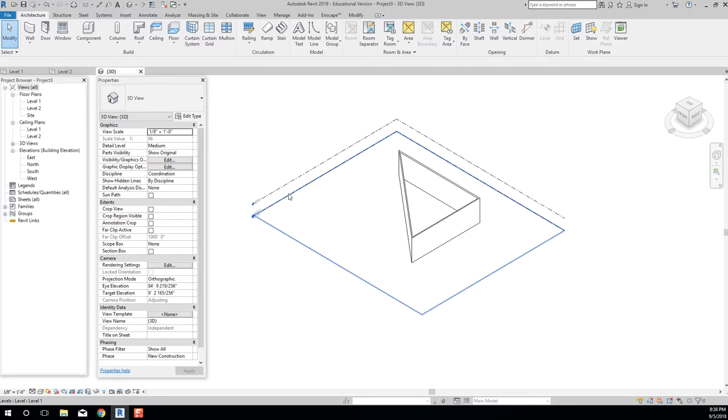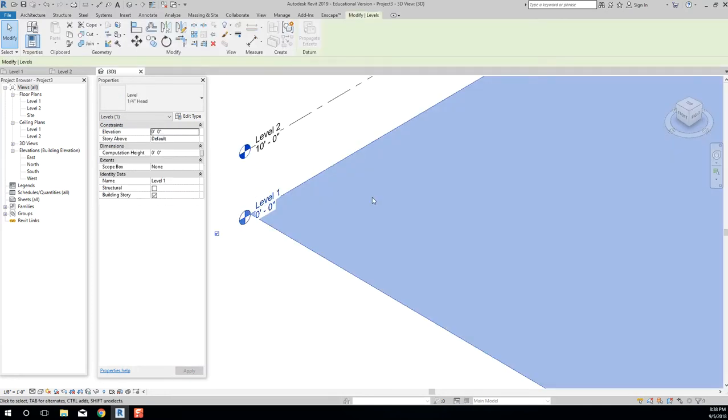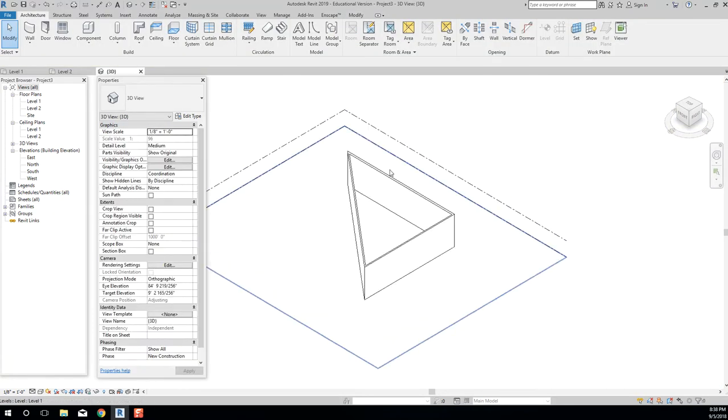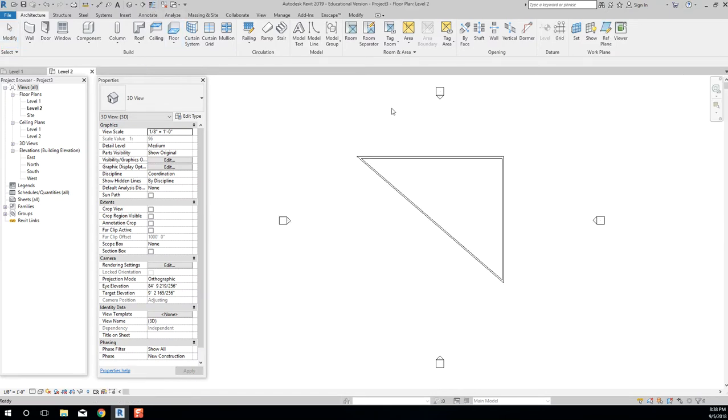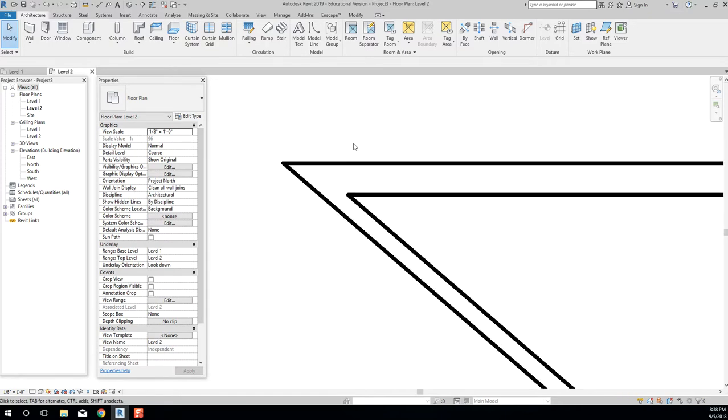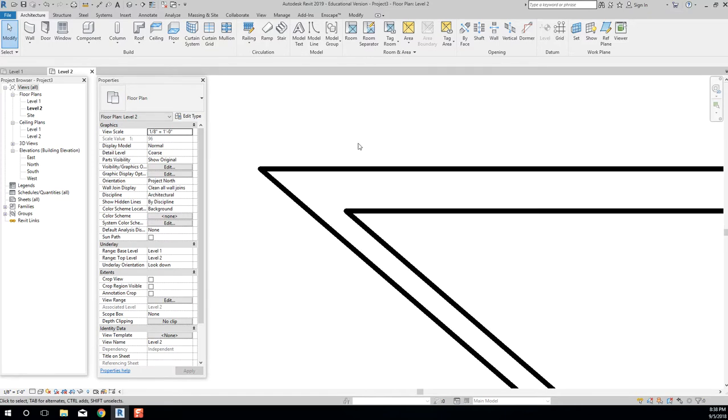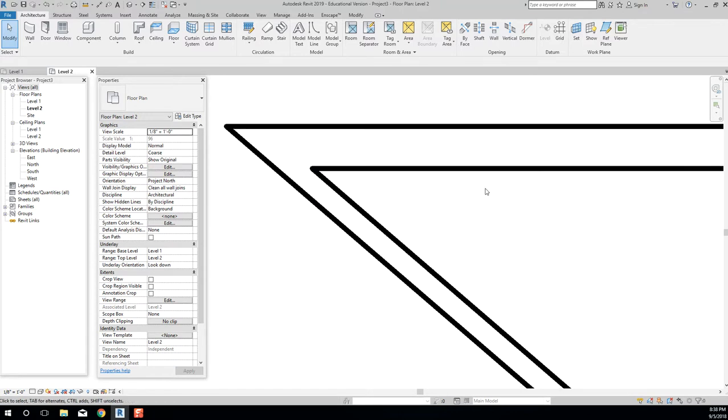Okay, well, that's kind of an odd little guy there. It also has a setting here. I'm going to show you something. Oh, you guys in AutoCAD are going to love this, right? Do you notice that as I look at my floor plan here that the walls already have a thickness associated with them, the wall lines? No more layers to define wall thicknesses, right? They're inherently built into your actual wall assembly, okay?